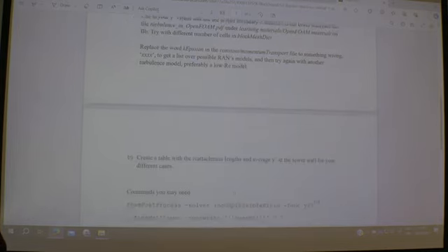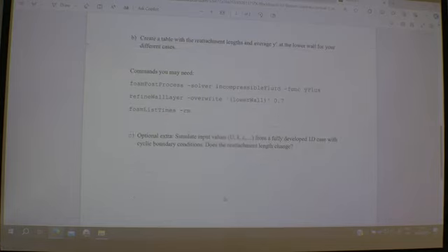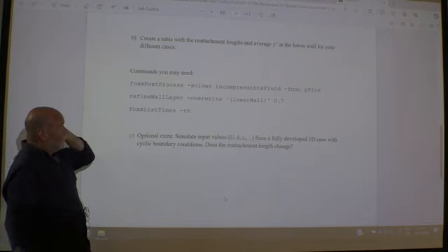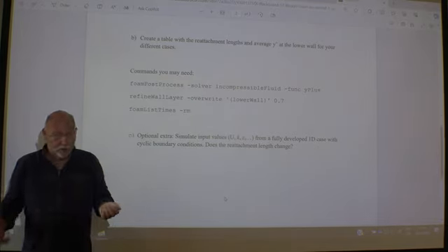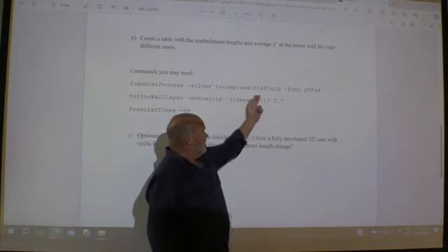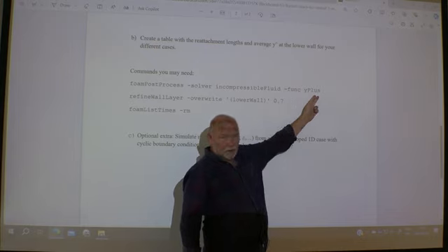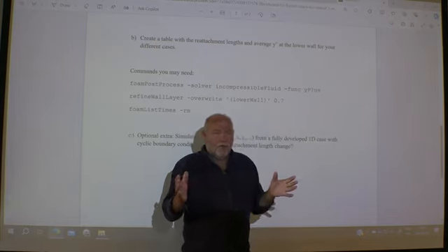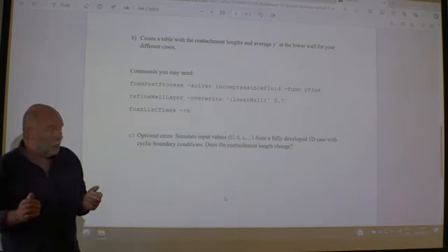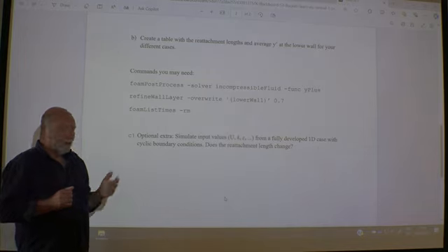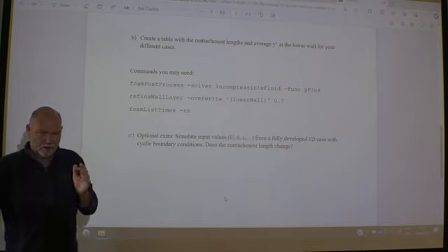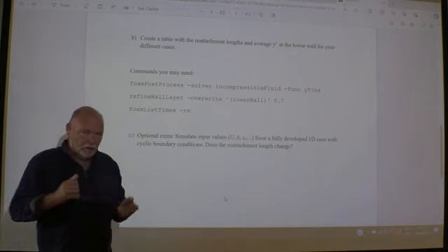And here you have some nice commands that you should be aware of. After you have done a simulation, you can execute this one, postProcess, and then -func yPlus. It will then report what's the average y plus, what is the maximum y plus, and you can even have a look at them in ParaView and see along the wall where the y plus is big and where it is small.